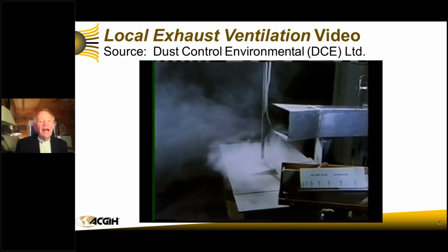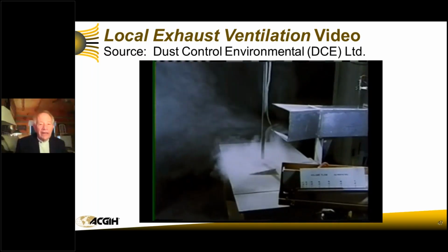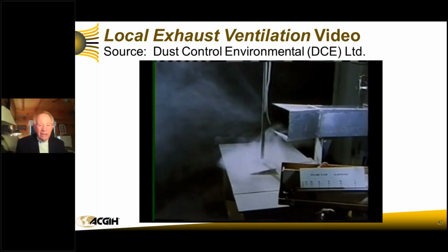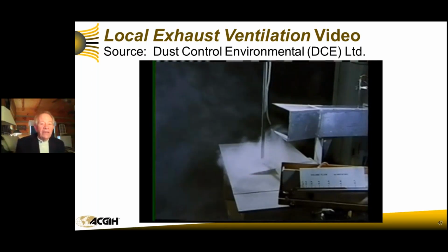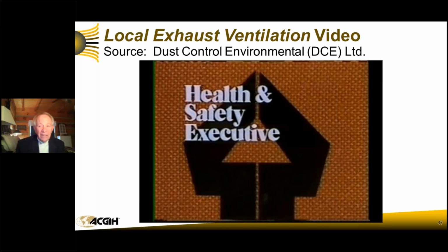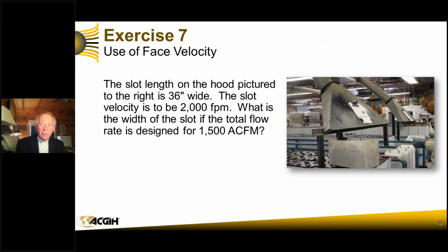Because what we're doing is allowing suction to happen in space, and when you suck in air, you're getting the dust that's behind your ear as effectively as the dust that is out in front of your nose. So it doesn't understand. Static pressure degrades, remember, in all directions, and so air will come from behind, as well. You cannot project suction in a direction.